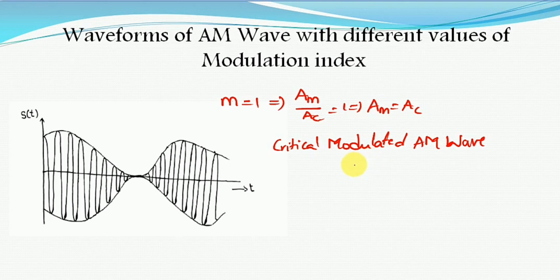In this case, some information will be lost during transmission, or in other words, there is a loss of information in recovering the original signal at the receiver. That loss of information may occur because of the modulation index value or the high strength of noise present in the medium. Practically the under modulated AM wave is used. Theoretically we can consider the critical modulated wave in some cases.